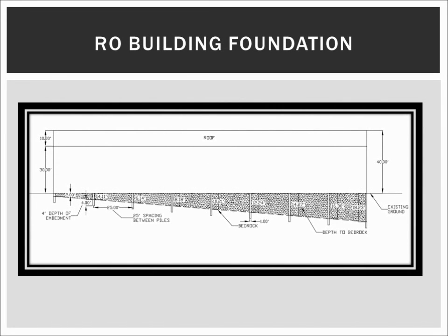After reviewing the soils report for our designated site, we decided that the best foundation method for the simple steel buildings would be to drill piles into the bedrock. Since San Diego is located near 2 earthquake fault lines, an earthquake is always a potential threat to building integrity. By drilling the piles into bedrock, we ensure a higher factor of safety if a catastrophic event occurs. The foundation system will use multiple piles at spacings of 25 feet in each direction with piles on each corner of the building. This is done to ensure that the load is distributed evenly across all of the piles.